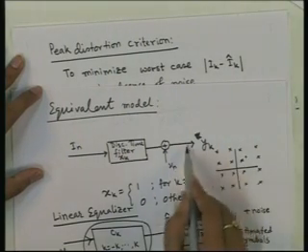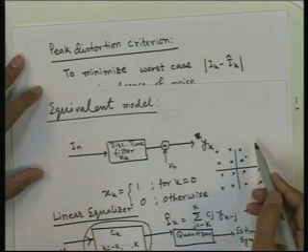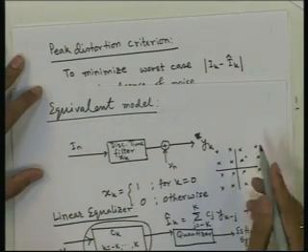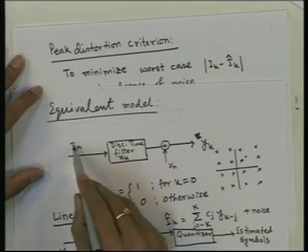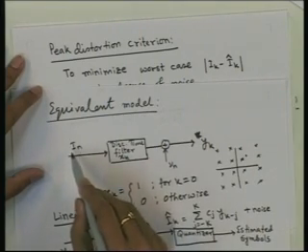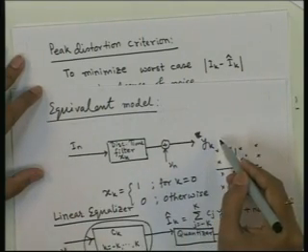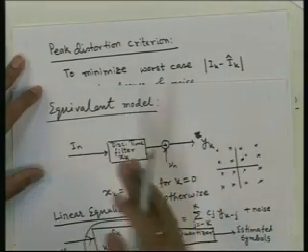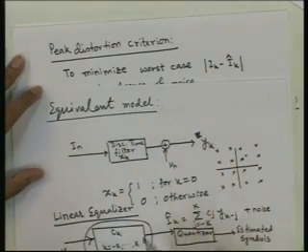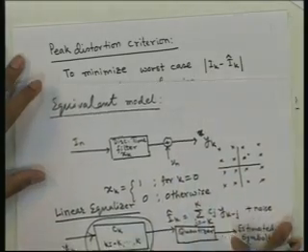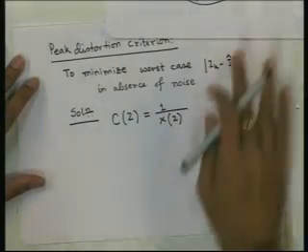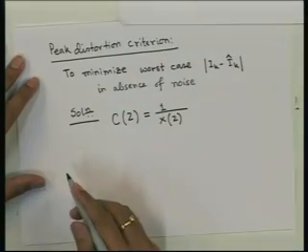This noise also will go through the same filter, and at the output there will be some other sequence of noise. And at least the signal part will be recovered fully. There will not be any intersymbol interference left between the output samples. So, that is the inverse filter solution for the linear equalizer.